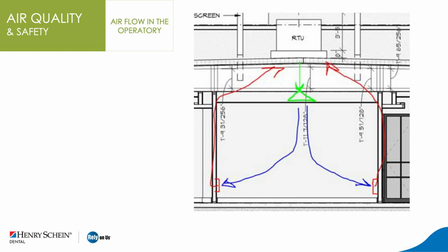Now, this particular schematic that you see on the screen is generally employed in warmer regions of the country, because the biggest thermal challenge most of the year in those areas is heat. But in more northern climates where the weather is much colder, much longer, the most common practice is to place the air supply grates at or near the floor and the return air in the ceiling. So it's just the opposite of what is on the screen.